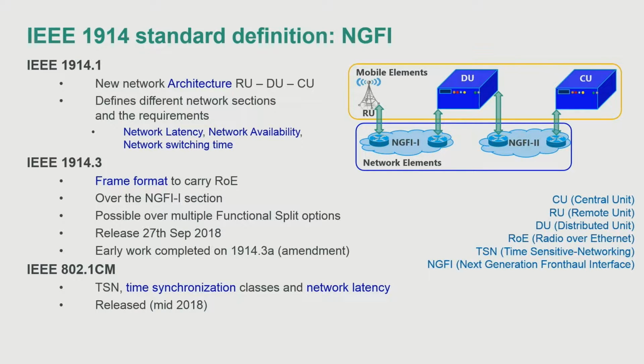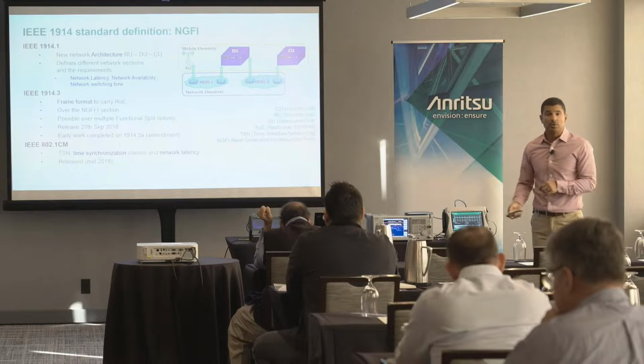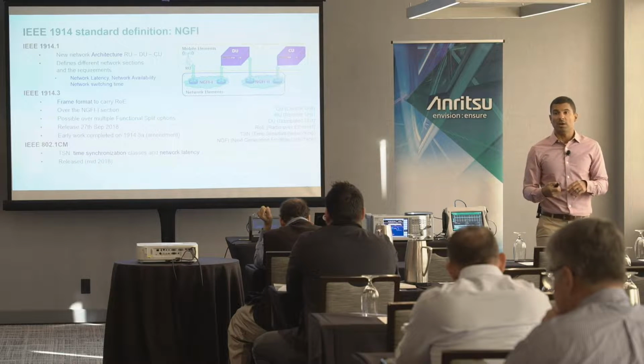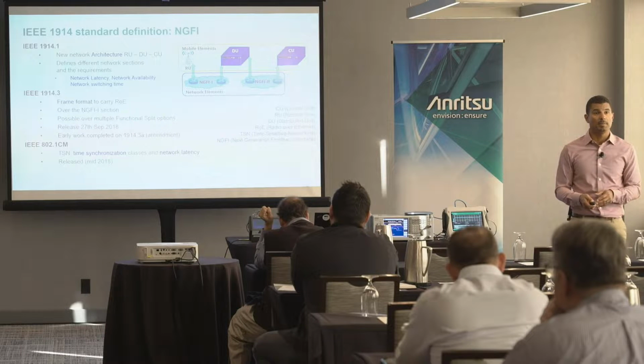You'll see here, instead of calling it a baseband unit, they broke the functions up into 2 different applications. The DU, which is the distributed unit, that's where you're terminating your RF data, your IQ. And then the CU, the central unit, that's where it's sending out and distributing your IP data, your user data.